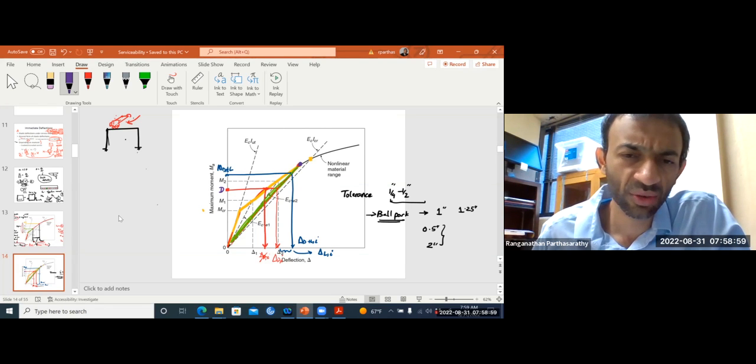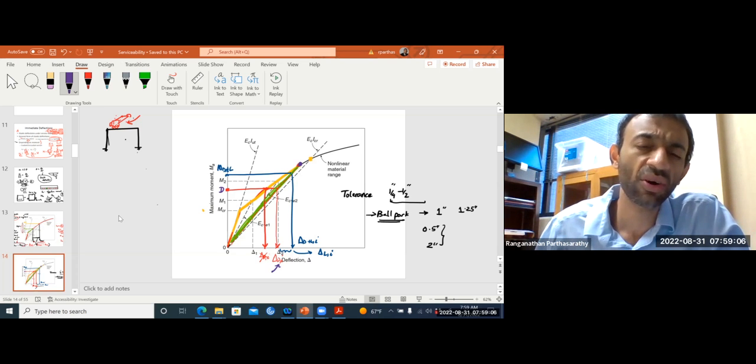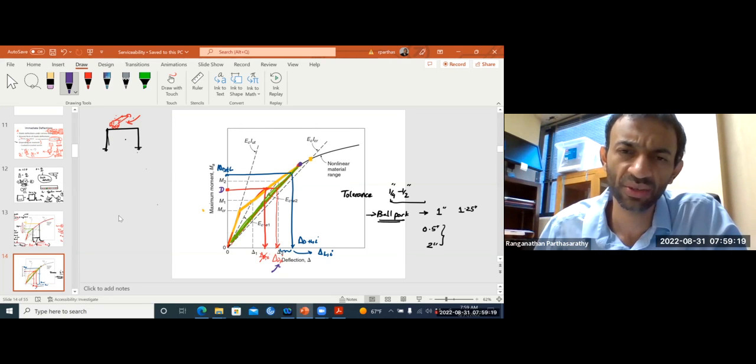This is your dead load. Now, will you use the orange curve? No, you're going to use this green straight line because it already saw the loads which are much higher than what is coming in after that. So it has cracked to as much as it would. It's not going to get there anymore from now. So this point is your instantaneous deflection due to dead load.